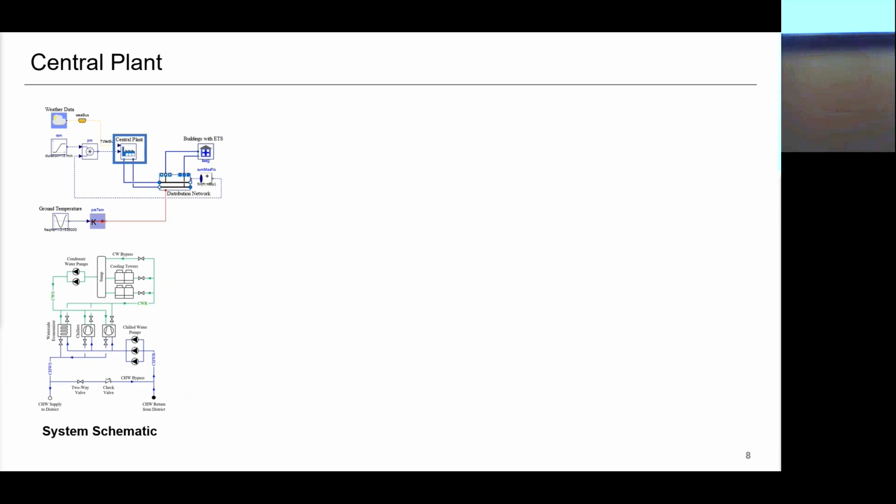Yeah, to be honest, we need to look into the detail again, how it's modeled, in particular in this case study here. But we do have models now for the soil temperature, and typically it's a lot of hand waving how to do that properly. But if it's insulated pipes, you typically model the insulation, and you can always model part of the soil and then assume undisturbed soil temperature if you're far enough away. That's reasonably accurate, I think, for this typical district cooling system.